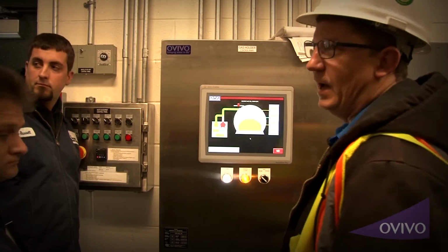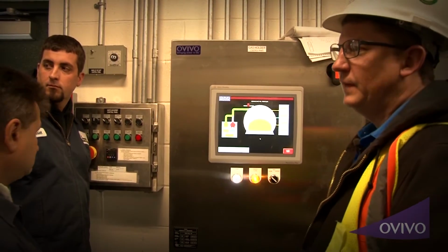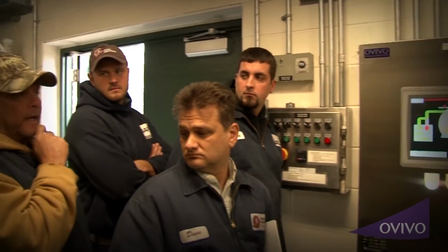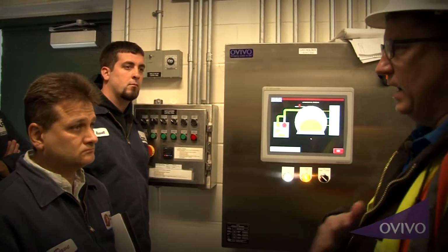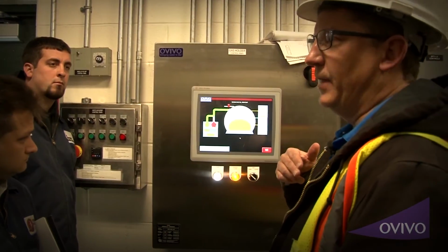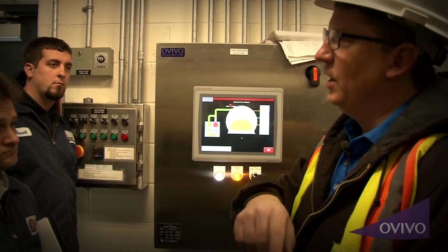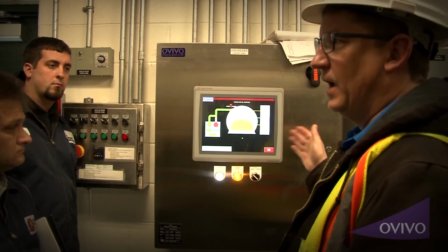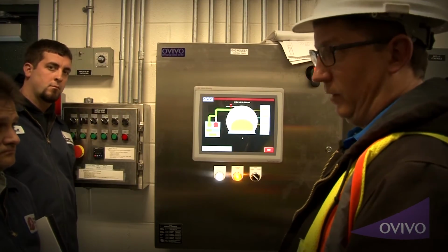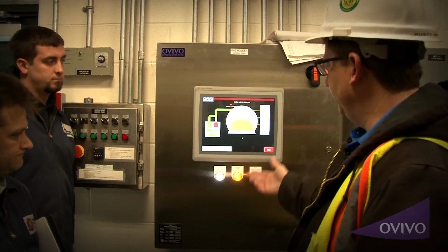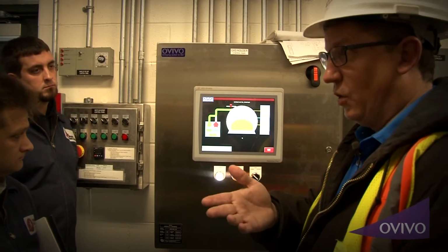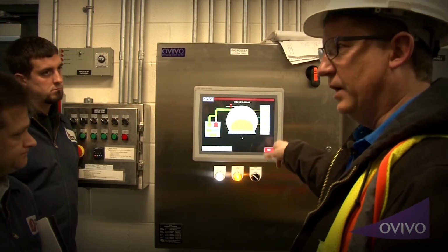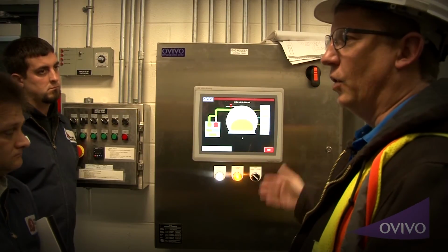I got a question. We're running on blower 1. Four days from now, it's going to switch to 2. If it doesn't come on, does it automatically switch back to 1? If anything were to ever happen to any item on there, if somebody were to turn the fan off that was running from down there in the control room, it automatically cycles to the next fan. It automatically turns on the next fan and then alarms and says, I have a blower fault. At which point, you would fix the situation, turn the blower on, acknowledge the alarm and hit the reset button on it, and everything would come back to normal.